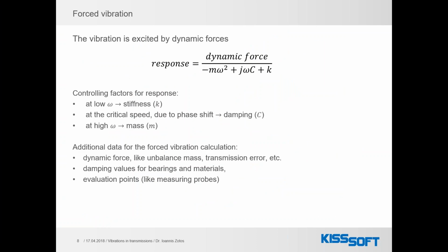I'm going to talk briefly about forced vibration, so I'm going to move to the second main subject of this presentation. Forced vibration is actually the calculation of the dynamic response of a structure due to a dynamic excitation force. This is the simplest equation describing this response in a simple mass-damper-stiffness system. With this equation, we can briefly understand how the structure is vibrating for different vibrating frequencies.